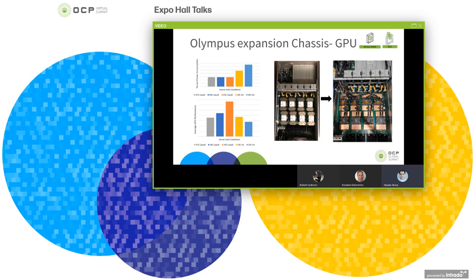Similar to the CPU case, we ran an investigation whilst running neural network type workloads provided by the Microsoft GPU team. In both charts, light blue and yellow columns represent the air-cooled permutations for cases of 35 Celsius and 25 Celsius air respectively. Orange, dark blue, and gray bars show data points for the water temperature sweep.